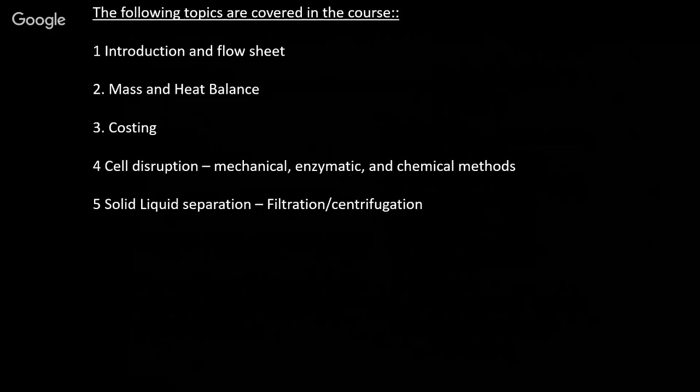Then came solid liquid separation. So different types of techniques are there. We talk about sedimentation, coagulation, and settling, then there is filtration, there is centrifugation. So all these techniques deal with solid liquid separation. Then we looked at the design equation like Darcy's law.